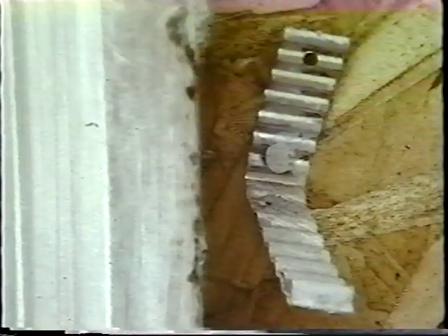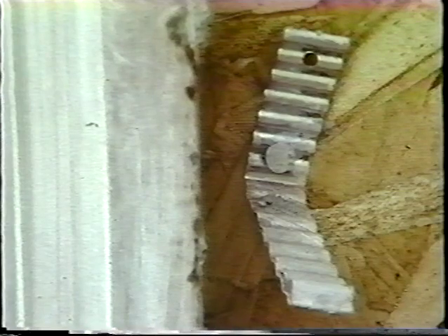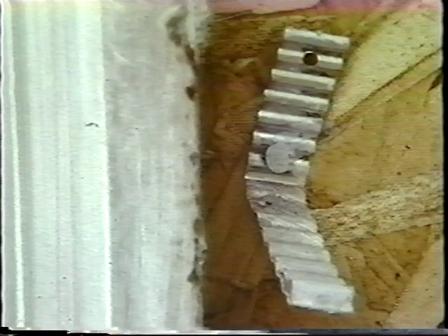Corrugated metal ties are the most common type of tie found in residential construction, but corrugated ties require close attention paid to their installation. To be effective, the nail used to attach the tie to the stud must be very close to the bend in the tie. If not, the veneer can move too much before forces are transferred to the framing, causing the brickwork to crack.